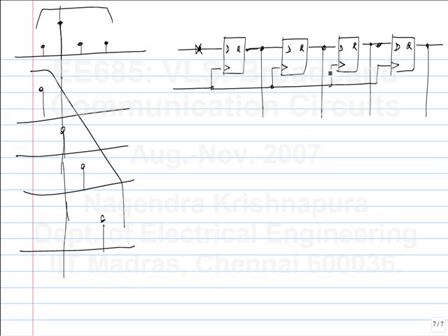Then what do we do with this? I have generated these 4 and I want to get this. How do I make the weighted summation? I mean the implementation of the weighted summation. I already know the values of these, let's say, and I want to implement the weighted summation. What do I do? You can imagine CML flip-flops for these, in which case each of these lines is differential, the clock, data and Q. If you want, you can imagine that. So tell me how we will implement the weighted summation. What are all the ways of implementing weighted summations?